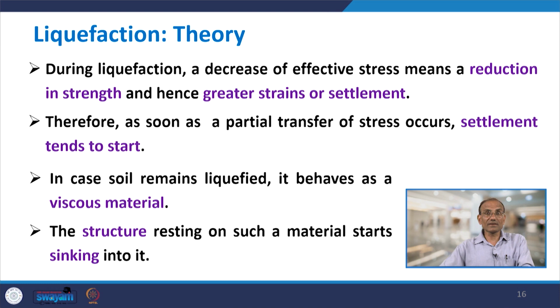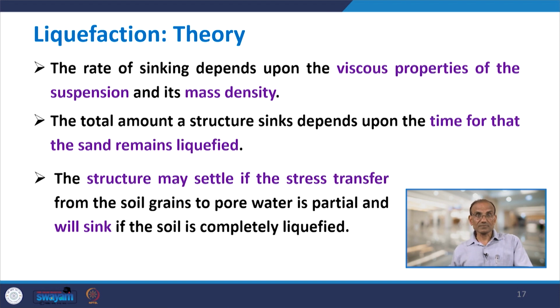In case the soil remains liquefied, it behaves as a viscous material, and the structure resting on such a material, where the soil behaves like a fluid, starts sinking into it. The rate of sinking will depend upon the viscous properties of the suspension, that is the soil material, and its mass density.